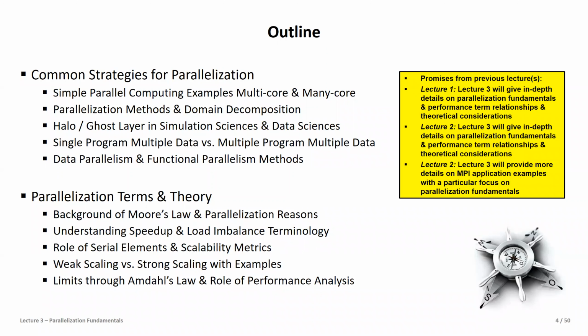Then we have this interesting phenomenon that at some point in time we reach the end of the core space or the memory space. So we have to have something we call the halo and ghost layer that makes us able to store some variables that we want to communicate maybe in the next time period to the next processes next door. And we will talk about this specifically in this lecture today, where we also differentiate between